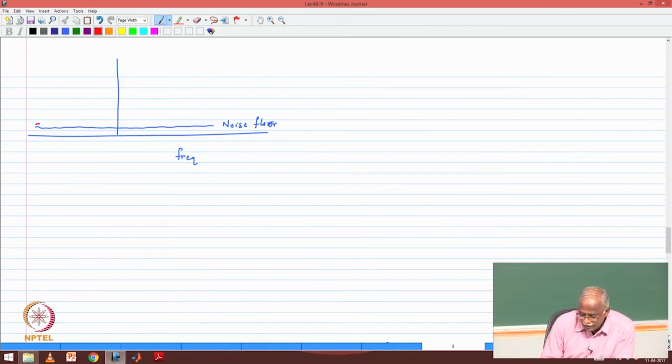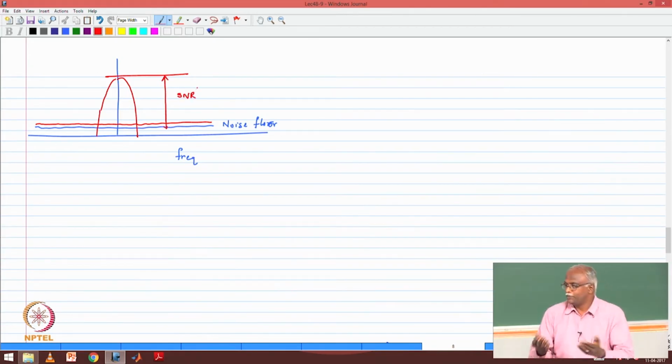You take a narrowband signal and then you spread it. So basically the noise looks like it became slightly higher because you spread the signal. At the receiver, what do we do? We despread this signal. The despread signal looks like this. My SNR is with respect to the noise floor, only one. So this becomes my signal to noise ratio. Spreading, despreading. What happens in spreading? What happens in despreading? Are you clear about this?